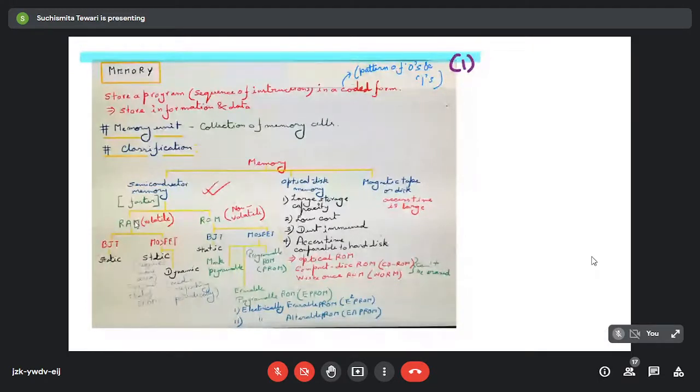It doesn't mean that if I have written to a memory location first, then the least access time is needed there. No, it is nothing like that. You can store the data in any sequence you want, but while retrieving the data, the time will be the same in all the cases. So that is why the name random access memory. And this is a type of memory where you can easily write as well as read. So alternatively, it can be termed as read write memory or RWM.